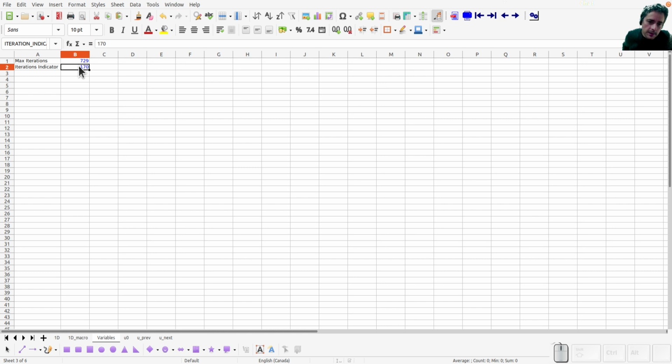We could run this if we set it up, do a few tests, go have dinner, and come back and the calculations are done, and we have a pore pressure distribution. You could do that for a slope. If you want to evaluate the time rate of flow of water, you could set up that kind of problem.